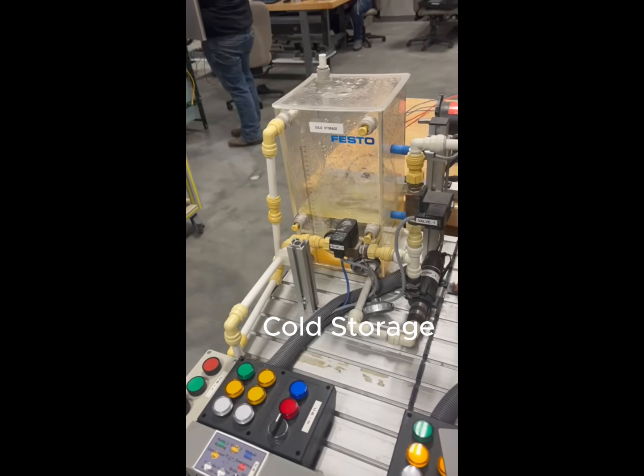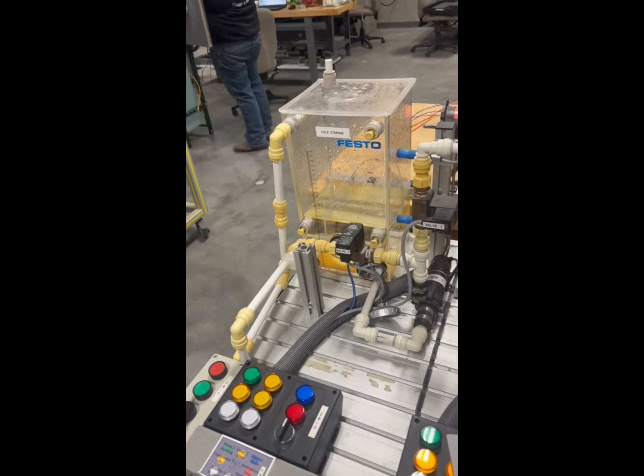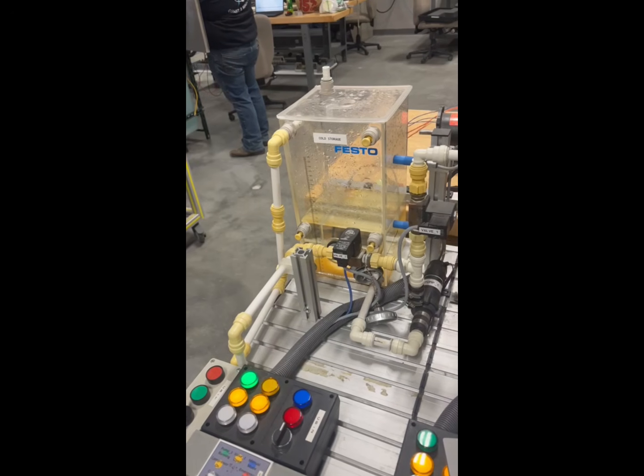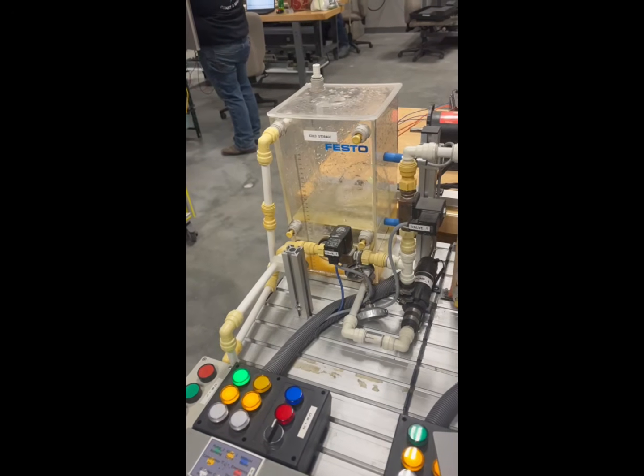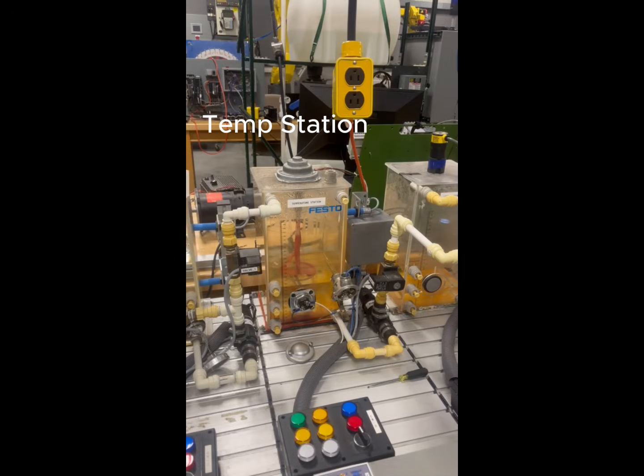For the first part of our process, we have the cold storage, where it's going to recirc water as long as it's in a good level to cool the water down to a specific set point that is adjustable through the HMI. Once the cold storage is at a good level and the water reaches a good cold set point, the temp station will begin filling up.